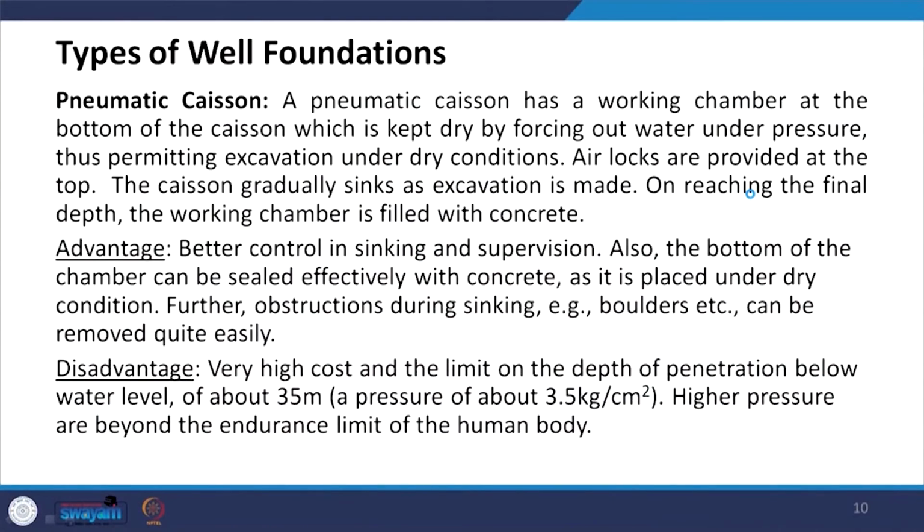So, this will work like a cofferdam also. Air locks are provided at the top. The caisson gradually sinks as excavation is made. On reaching the final depth, the working chamber is filled with concrete.